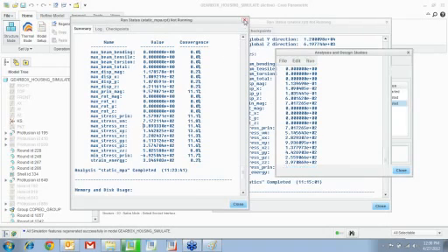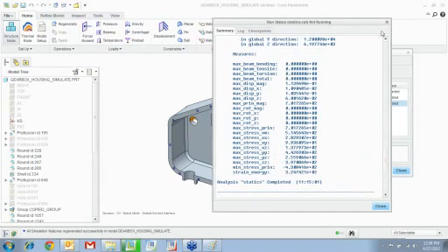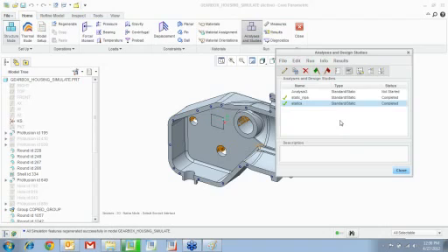right? So a single pass has pretty much allowable convergence of 10%. With a multi-pass, you can basically go ahead and change that allowable convergence to 5%. Typically, most people who use Mechanica stick to 4 to 5%, unless it's a part that you're going to run optimization on and you're really concerned about it. You would go ahead and run it at 3 or 2% also if you want to.